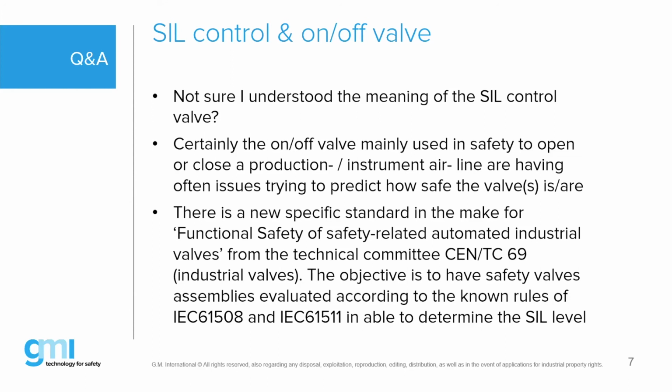Well, yeah, I have a comment. Coming to the question, how can you certify a body? We have requests where they want the SIL certificate for the cabling or for the terminal block. For mechanicals, if I read the standard correctly, it is about functional safety of electrical, electronic, programmable electronic safety-related systems, not a valve body or a wire. But as you correctly mentioned, a valve consists of many parts, and we have to look at the complete package to know what you're trying to achieve.